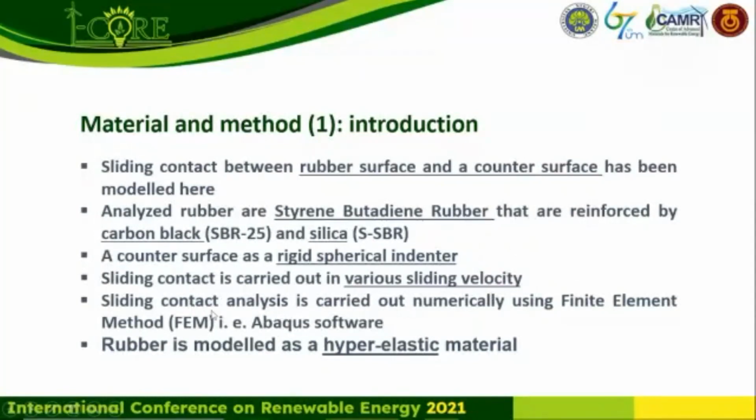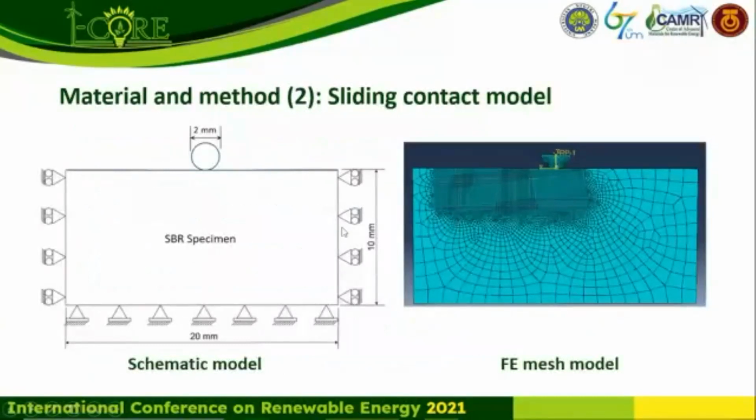In this case, my sliding contact analysis uses the finite element method. We use Abaqus software produced by Simulia. And the rubber is modeled as a hyperelastic material. In this software there are some options for material type, so we choose a hyperelastic material.